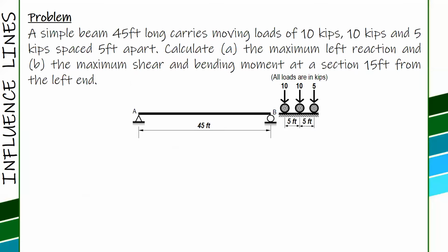Another is a series of concentrated loads. How do you analyze or determine the maximum function for a series of concentrated loads? So a simple beam 45 feet long carries moving loads of 10 kips, 10 kips, and 5 kips spaced 5 feet apart. Calculate the maximum left reaction and the maximum shear and bending moment at a section 15 feet from the left end.